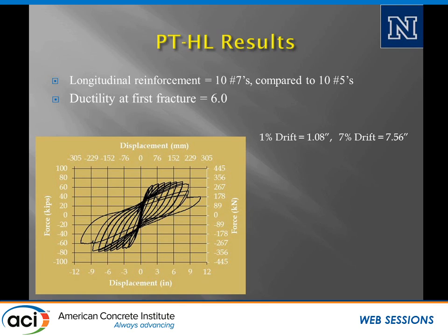In this case, you're not getting much of a reduction out to about 9%. This is displacement. The drift is essentially 1-to-1. So 7% drift is 7.56 inches of displacement. So we're at 8 and 9% drift. Again, we're getting very good displacement properties.